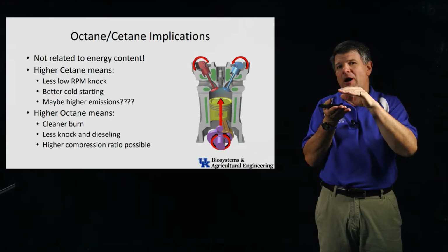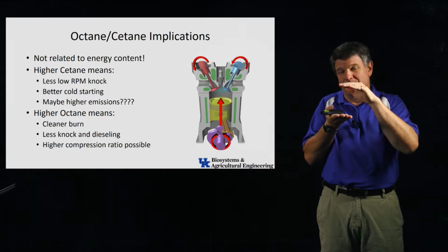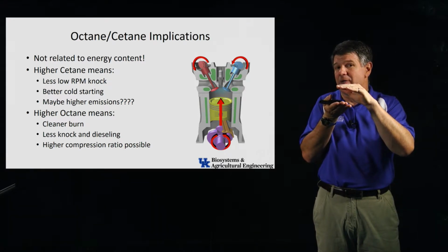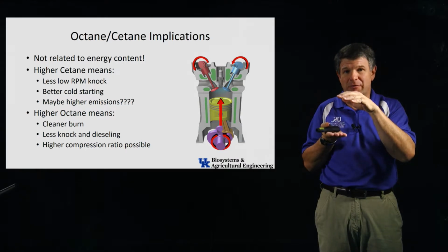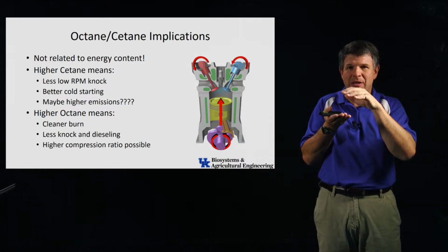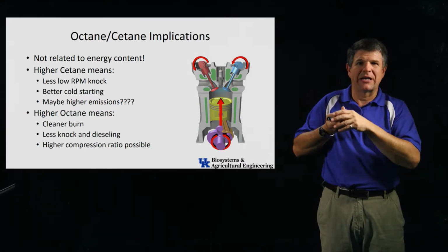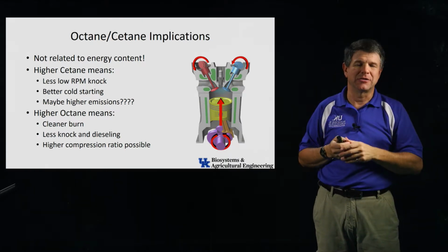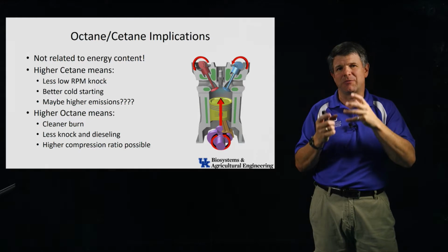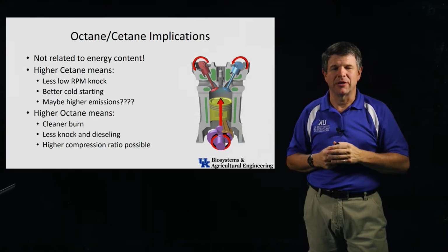But if I put a low octane fuel in there, and that piston's coming up, it might hit that auto ignition pressure before I give it the spark, and it's going to burn at the wrong time. And if it burns while the piston's still coming up, that's where you'll get a force pushing back down on the piston, and when the crankshaft comes up over the top, it does some weird things, and that's where you get some knock and hammer and everything like that.